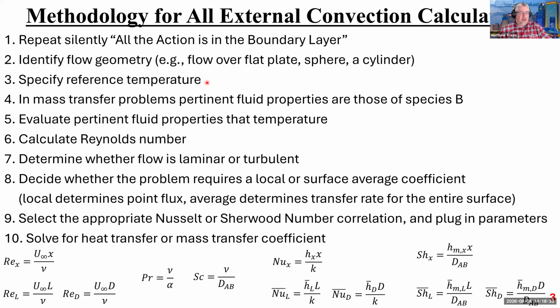Next, you're going to specify the reference temperature. I have a slide on this. Typically, the reference temperature is called a film temperature. It's the average of the temperature of the object that's undergoing heat transfer and then the free stream temperature, but sometimes not. So we'll dig into that a little bit more.